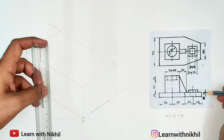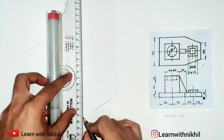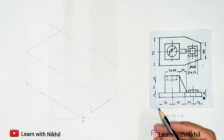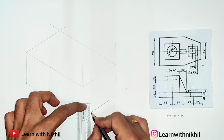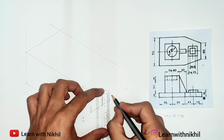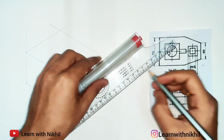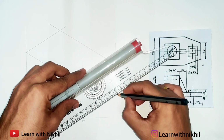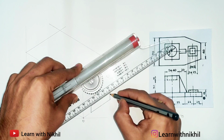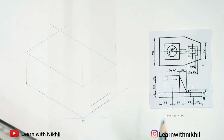Now next, in this view you can see you have a height of 15 millimeter, but that is not the height we require right now. We require the height of 10 millimeter, which is given at the back. So this height is 10 millimeter. So marking here the distance, you can make this dark, 10 millimeter. Then again from here also it will be 10 millimeter. Now joining this, taking this line as the reference line, draw the parallel line here and you can join this part. So side view is not given, so this you will not see. This is the 40. Then you have the slant lines.